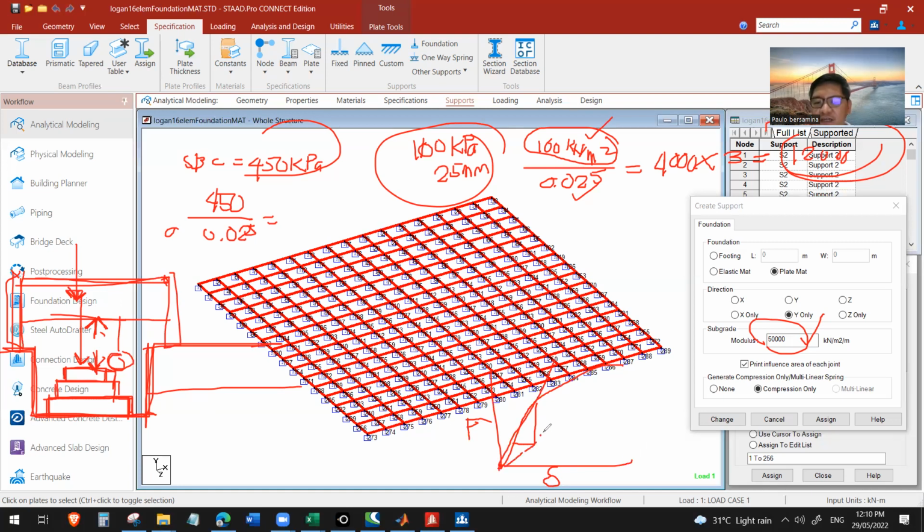Anyway, in the literature there is also a second modulus. But basically it is the slope of that load deflection curve. You can see that when the soil is soft, the subgrade modulus is low. So that's how geotechs obtain the subgrade modulus. The other way is through correlations,